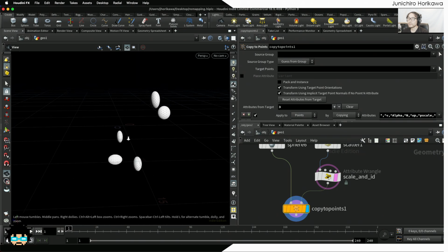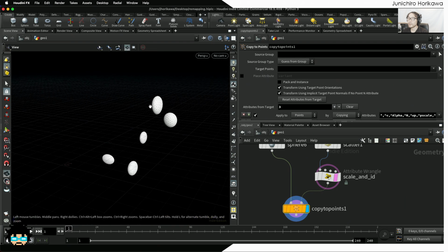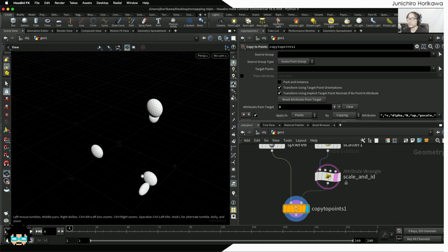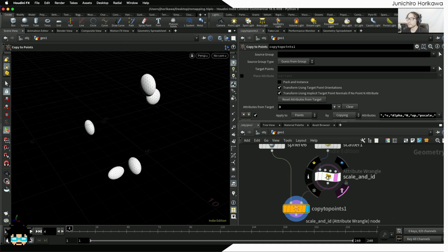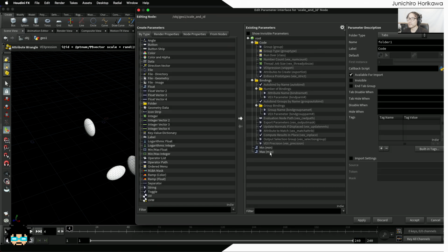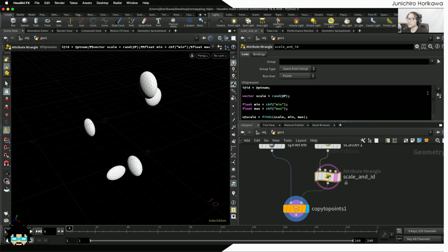And what I would like to do now is to move one sphere to the next numbered sphere, by changing its shape using a lerp one by one during this time frame. That's what I would like to do. Now let me increase the size a little bit. In terms of the scale, let's change the maximum range to 5 as maximum.